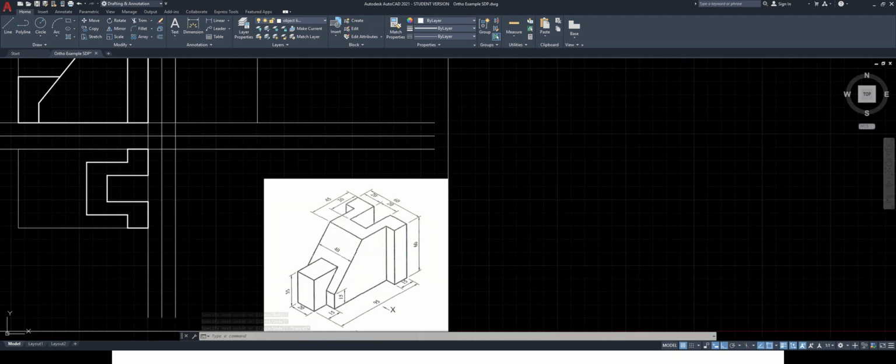Now this inclined edge. Whenever we are having any inclined face, in 2 of the views it will be seen as rectangle, and in third view, which is parallel to the observer, there it can be seen as inclined line. So for now, in top view, it will be seen as rectangle of what size? 40 by this length that we can get from here.